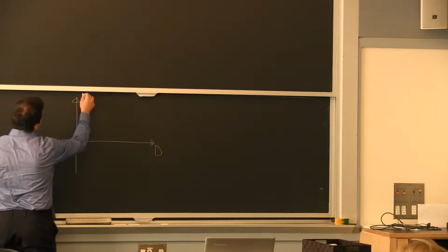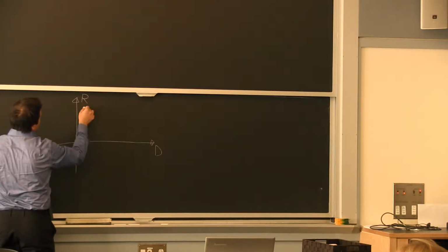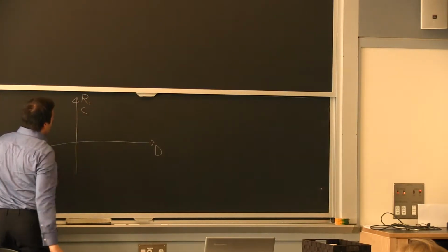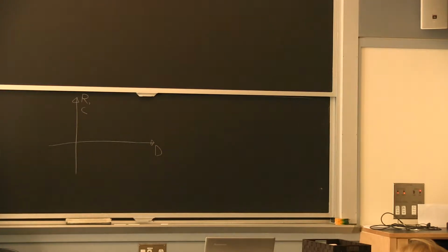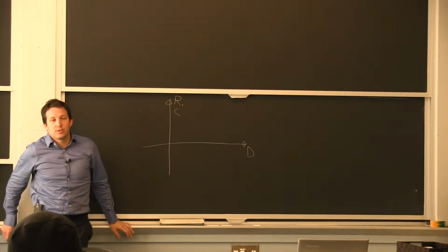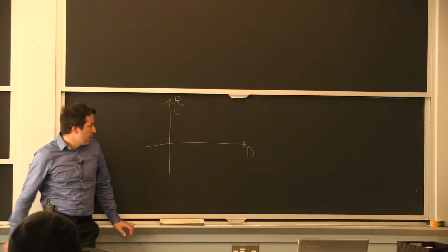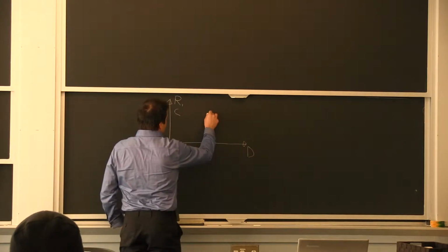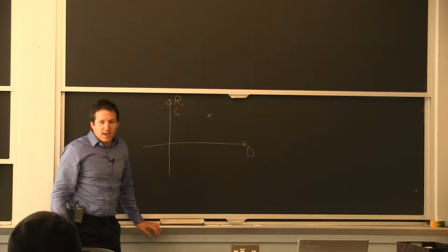And then you have the resistance, or I like to call it the capacity. Maybe resistance is a good term because it does involve taking into account: do I have chemicals? Do I have chlorides here that will cause slow cracking? Or do I have any hydrogen that will cause embrittlement? And all those parameters influence the capacity or the resistance of the material to a given application. So I make my best estimate. This is where I think I am.